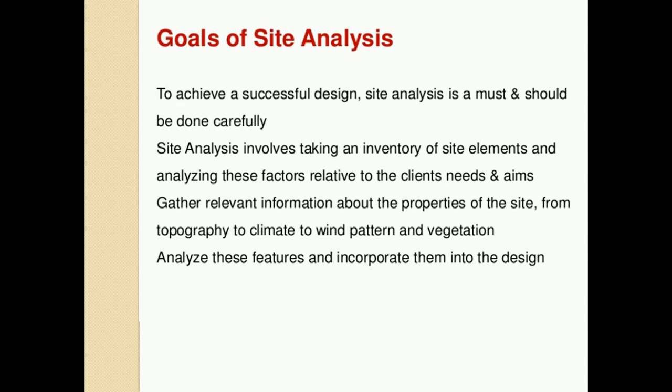See, there have to be goals for the site analysis. First one is it should be done very carefully. Then it involves taking an inventory of the site, just like the client's needs. As an engineer, we need to understand the requirements of the clients, their purpose of the construction, their needs, and as per that we need to gather the relevant information about the property from the site, then the locality, just like the past record, precipitation, topography, all geological information, vegetation, and then analyzing the old data we need to incorporate into the design.